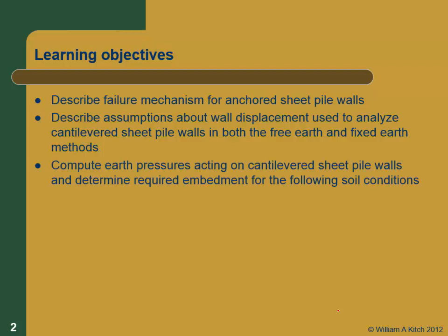solve it. And then you'll have to obviously be able to compute the earth pressures, and there are 3 different cases, and the earth pressure diagrams are different for each of them, just as they were for cantilevered walls. In a case where you have sand in the backfill and sand in the base, in a case where you have sand in the backfill but clay in the base, and in a case where you have clay in both of them.